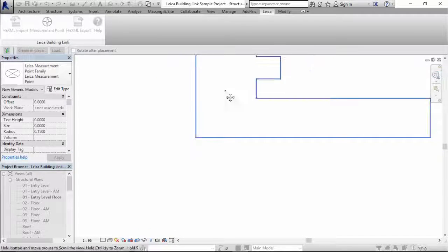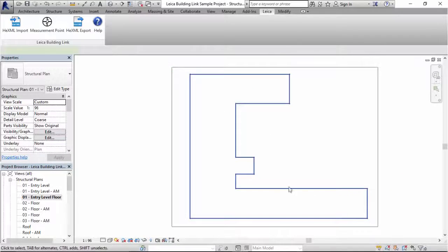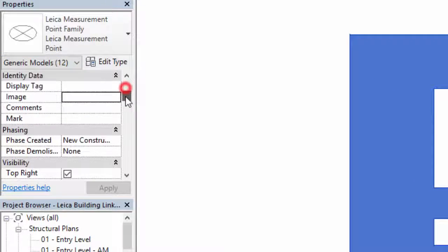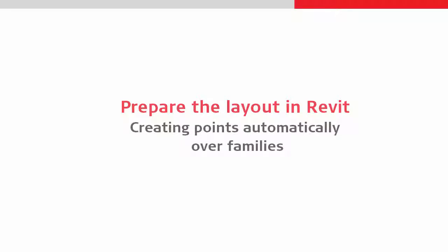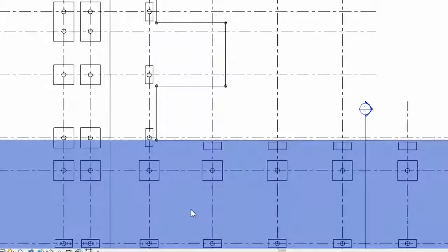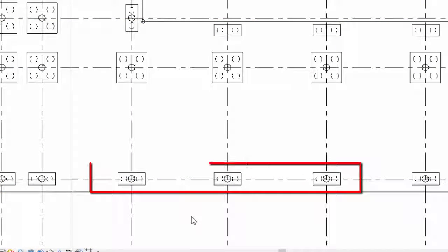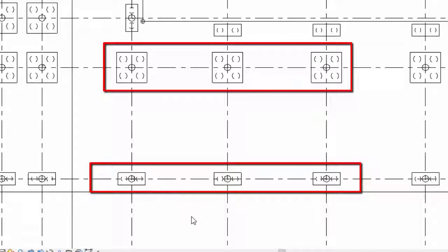For the points that this process creates, we can actually assign codes to the data. Here, we'll use a code CTRL for control. Now, this is not a mandatory step, but it is advised as it will make it easier to identify and filter this data at later stages. In addition to the control points, when on site, we will need the design data that we want to stake. In this case, that is the corner points from the 2-pile and 4-pile pile caps.